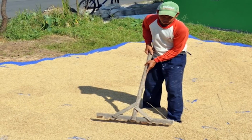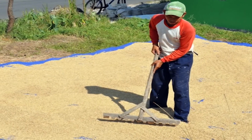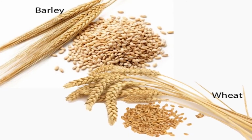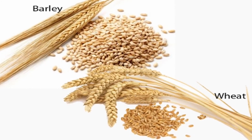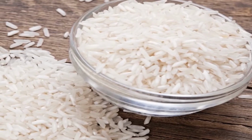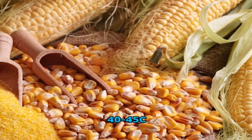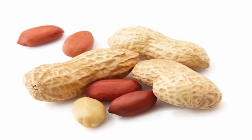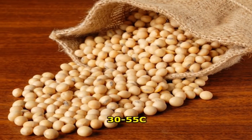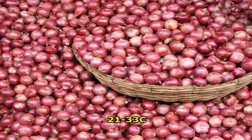If the temperature of the drying air is so important, then what are the recommended drying temperatures for various crops? In case of wheat, barley, the temperature is 43 to 55 degrees centigrade, while for rice it is 50 to 60 degrees centigrade, for maize 40 to 45 degrees centigrade, groundnut 36 degrees centigrade, soya bean 30 to 55 degrees centigrade, onion 22 to 33 degrees centigrade, etc.